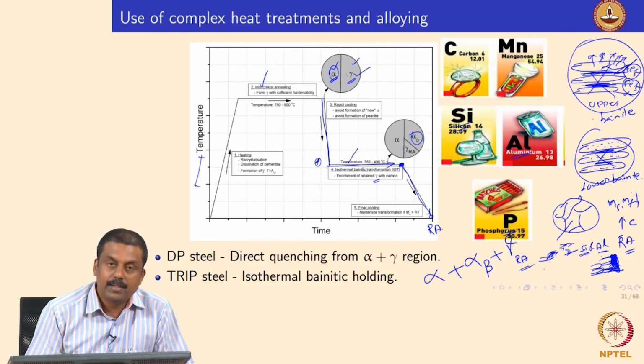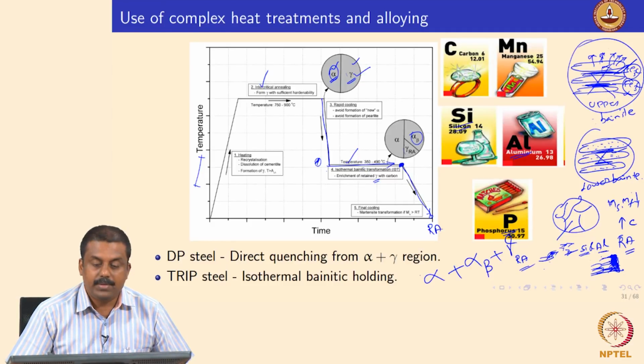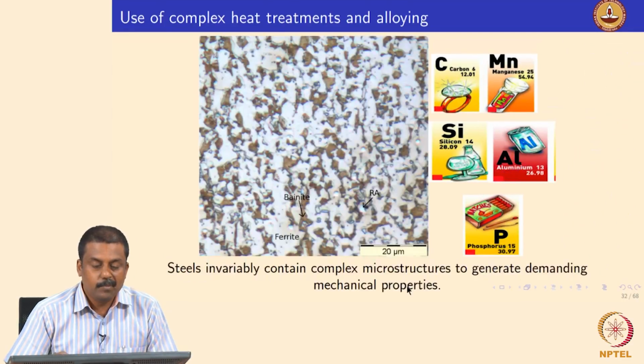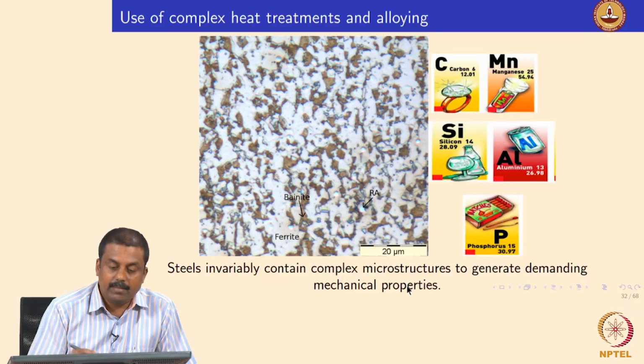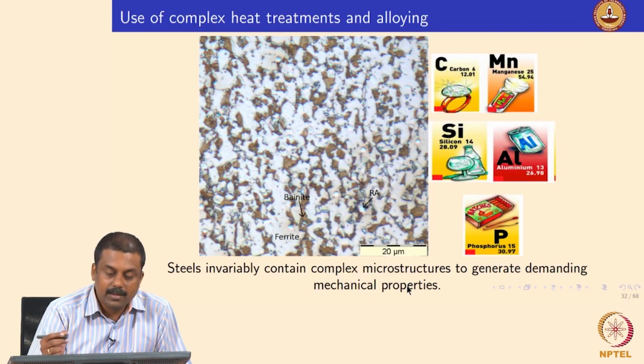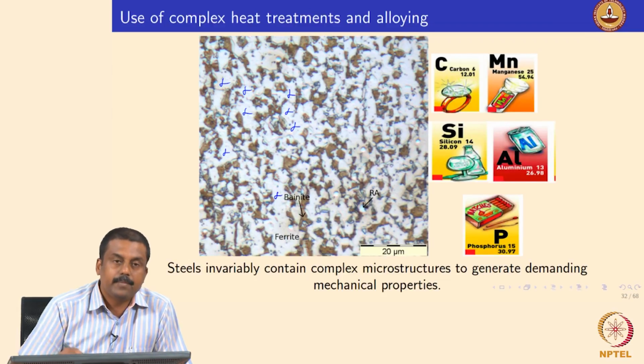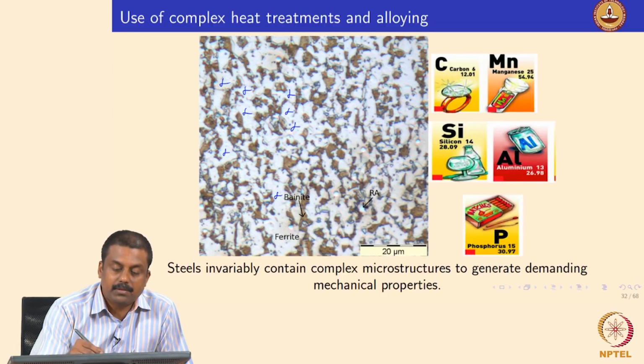Yes, it is clear. Okay, good. So, we look in further detail at the microstructure of TRIP steel. As I already explained, the typical TRIP steel microstructure is shown in this figure. We have ferrite, which is stabilized during the intercritical annealing, and you also have the austenite that is formed during this intercritical annealing treatment.